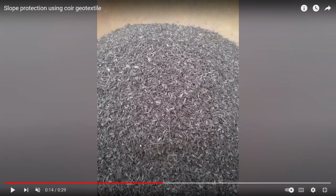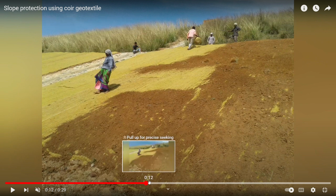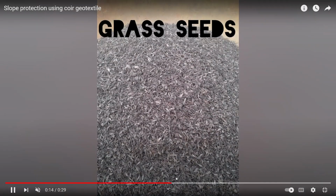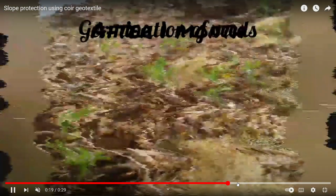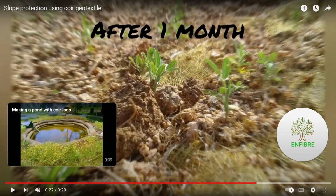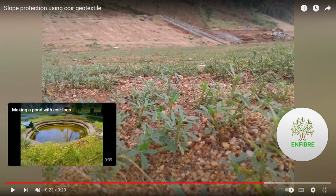Okay, so this is the slope. We put coir geotextile over it. Then you can put soil, and to aid the grass, you can put seeds on it. There will be natural growth of grass over the coir. Just after a month, you can see grass has started to grow.